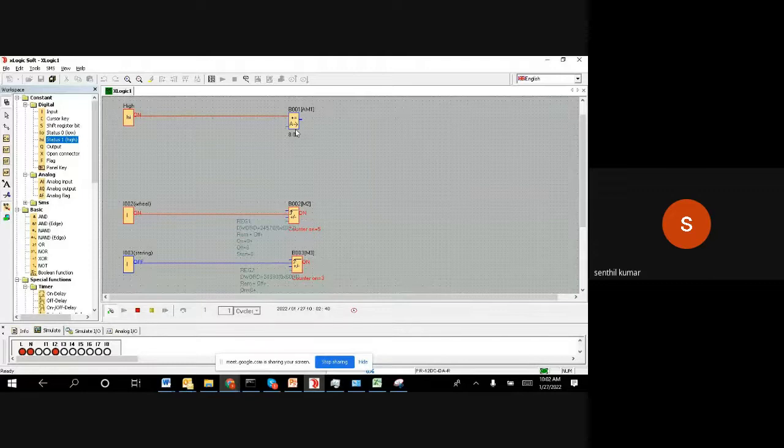Let us say, for example, just for the sake of understanding this requirement, once you produced a 100 number of total production, you can close off the day. That means there's no more production, you can stop all the machines. If that is a requirement, we take the total production here, and then we can compare it, and by comparing we can make the decision. The comparator output can go to the plant stop or machine stop or whatever, we can stop it. So the basic calculation is very simple.